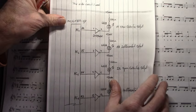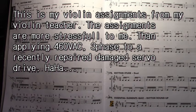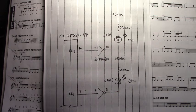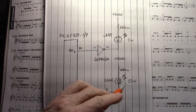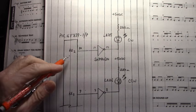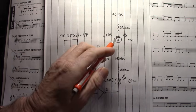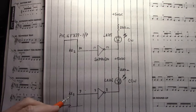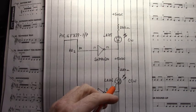Let's see what we got next. These two LEDs tell us whether our Hall effect or encoder pattern is running clockwise or counterclockwise. If we're running clockwise, port E bit 2 will turn on this LED. And if we are running counterclockwise, port E bit 1 will turn on this LED right here.